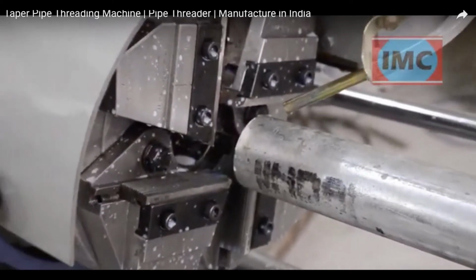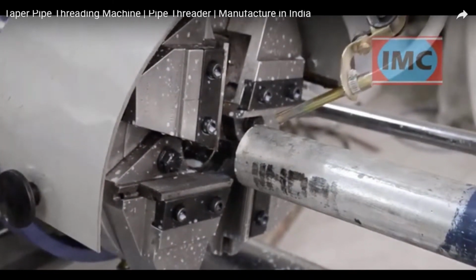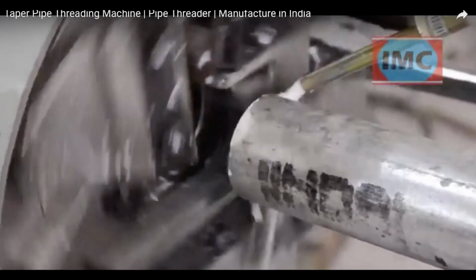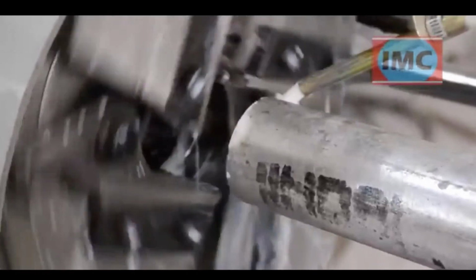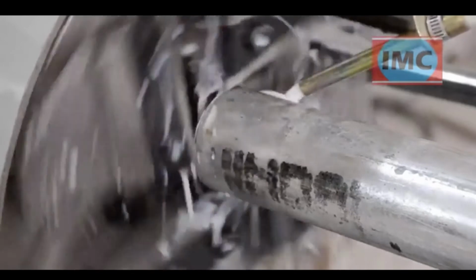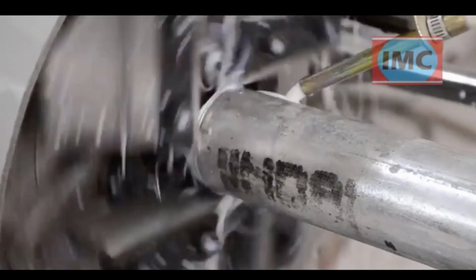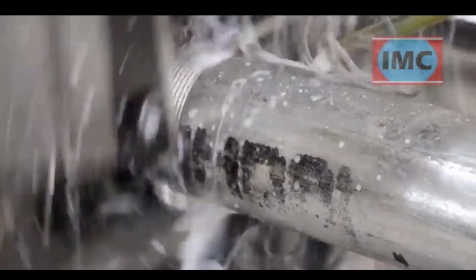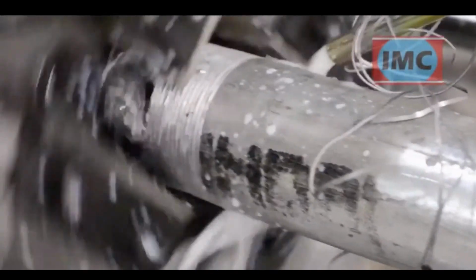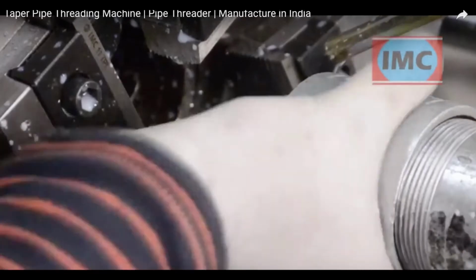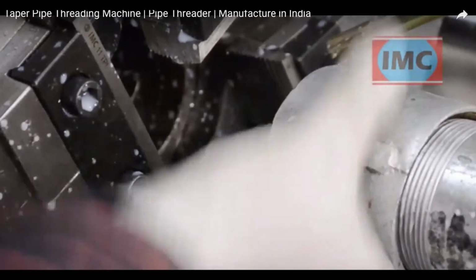Threading steel pipe is typically done with a Schedule 40 or a heavier walled steel pipe. When threading, you're removing a substantial amount of the pipe wall, in some cases up to 60%. Threading can be done manually with a hand tool, or like a roll groover, it can be done with a rigid 300 head and a set of dies. The dies are a set of teeth that will cut into the pipe and create the threads. Threads are designed to be tapered so that you can seal and torque against them.